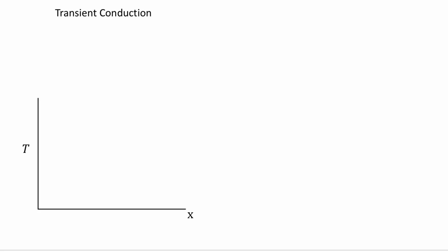So if you remember last time, last Friday, we talked about methods for solving numerical problems in 0D transient situations. Right? 0D transient means that we assume the entire body is at a single temperature. Now we're going to be talking about situations where the temperature is changing as a function of time, but there's also conduction happening within the body. Okay, so it's no longer 0D, it's 1D conduction.